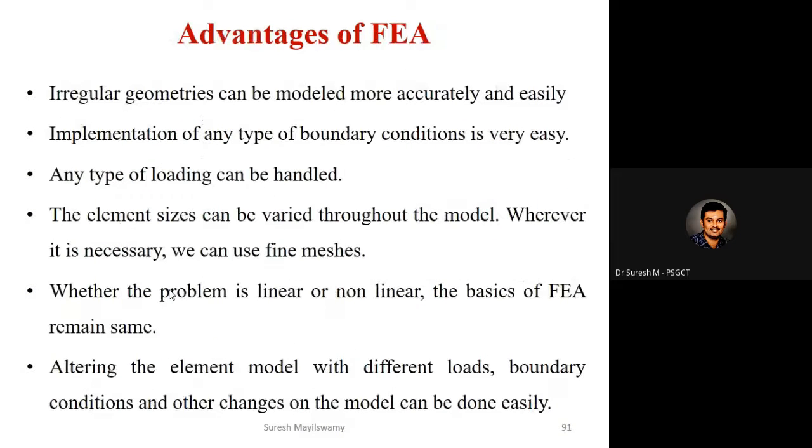Considering finite element analysis, the advantages are that irregular geometries can be modeled more accurately and easily. Implementation of any type of boundary condition is very easy. Any type of loading condition can be handled here. The element size can be varied throughout the model. Wherever you require, you can concentrate and do fine meshes there. If not required, you can do a coarse mesh.